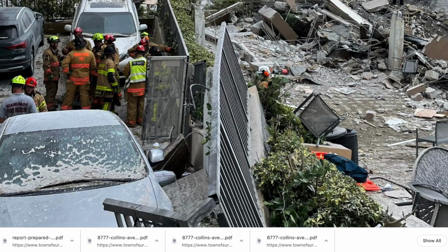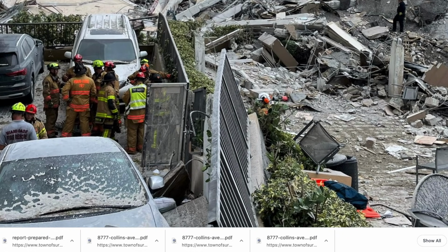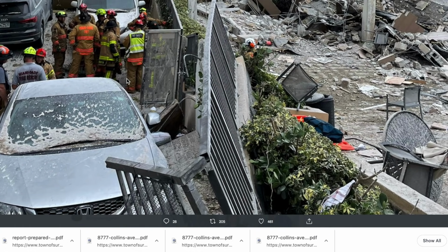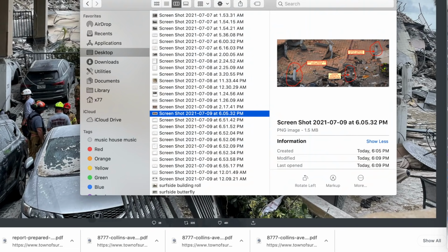And that bias is in the form of these vehicles sharing the same pool deck as the parking garage. So we got the pool deck rated at so many, is overloaded as so much, but then we also have the parking garage connected to it with these hydraulic forces of these cars coming there, slamming on brakes, parking, spinning out, driving, and creating a shock load all around that area. So that would be my bias point to have my epicenter, my beginning failure, along with the stresses, the spans, etc., the deck's area.